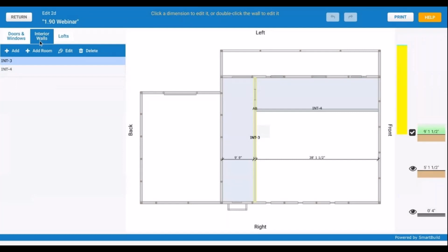Oh, we don't add stairs yet, Steve. Oh, ladder. Yeah, we don't add stairs yet. That's a good point. It would just be too difficult to actually put in stairs. You'll have to figure out where you want your stairs to end and the shape of the stairs. If you're going to have a landing, Sean showed you putting in a landing just at the halfway height. But you would have to do all the stair figuring yourself after the fact.